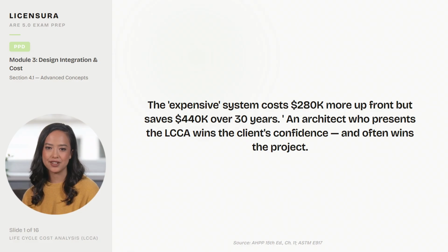The expensive system costs $280,000 more upfront, but saves $440,000 over 30 years. An architect who presents only first cost loses the argument to the contractor saying, "Go with the cheaper one." An architect who presents the LCCA wins the client's confidence and often wins the project.